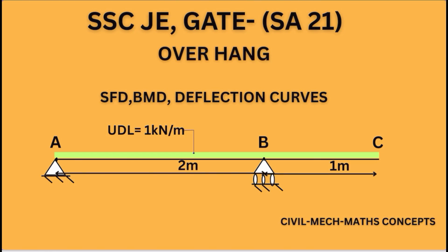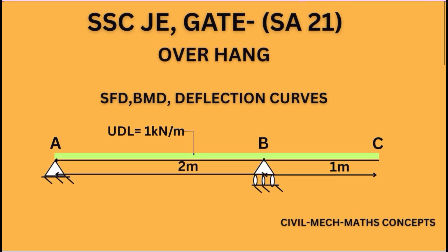And it's an overhang, and this is a pin joint, this is a roller joint, it's a free end. As part of the structural analysis, supports are concerned. I have already discussed in the last lecture about the supports and their properties. As far as pin joint is concerned, slope is not equal to 0, but delta is equal to 0. At roller joint, slope is not equal to 0, but deflection is 0. At free end, deflection and slope are present. In a fixed end, deflection and rotation both are absent. Now, for details of this, you can refer to my previous lecture.